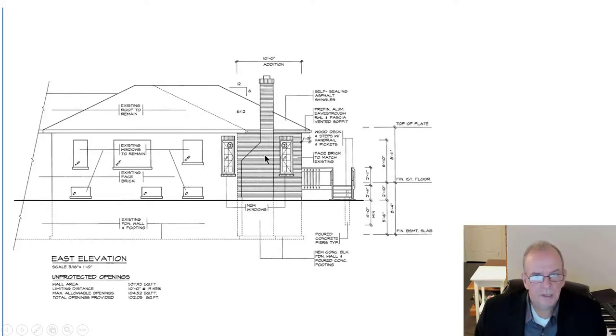There's the new brick. If I was doing the eaves trough, if it worked, and sometimes it doesn't, I would put my rainwater leader right here if I could, because that would hide the joint between the new brick and the old brick. It would give you a transition, so if there's a little bit different coloring in the brick, it doesn't stand out. It'll make it look a lot better. I would also save the brick.